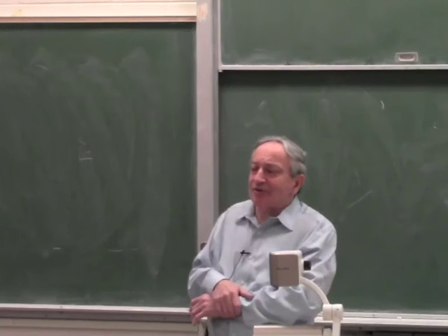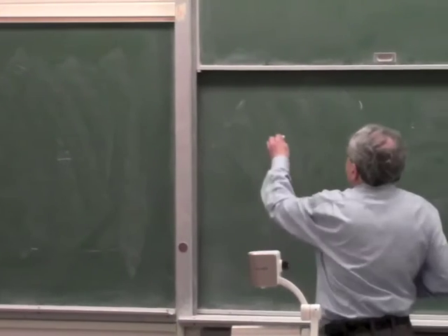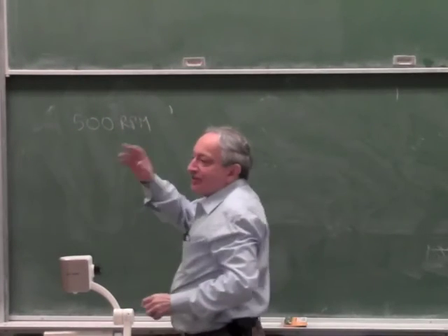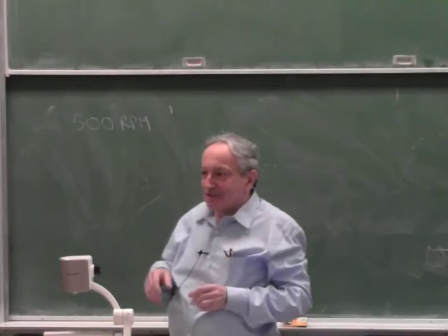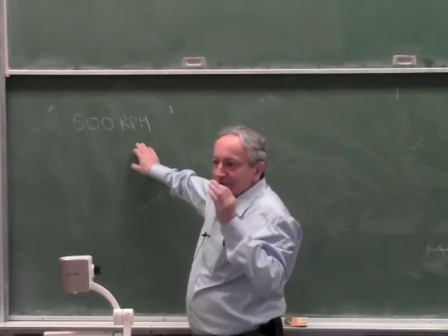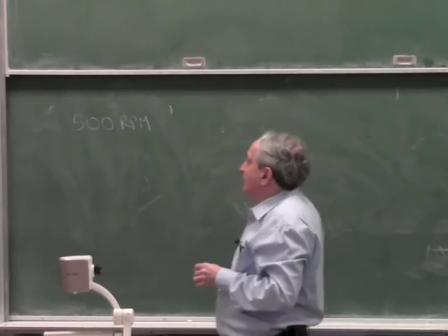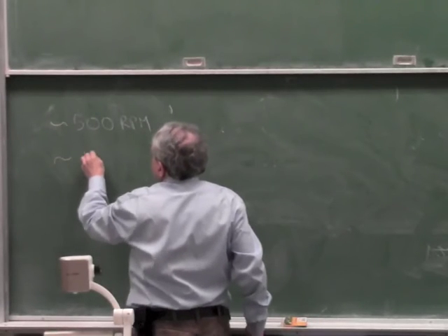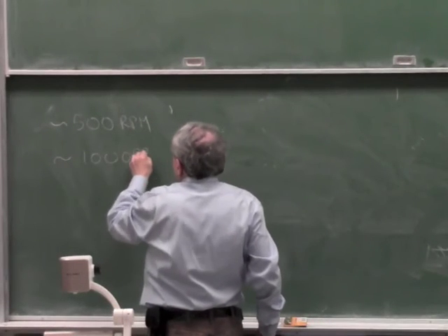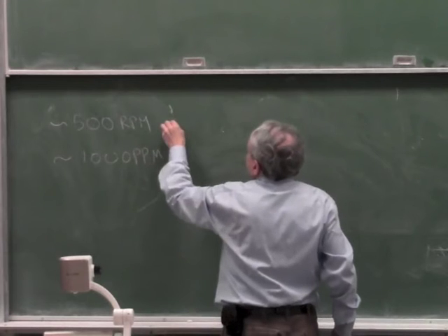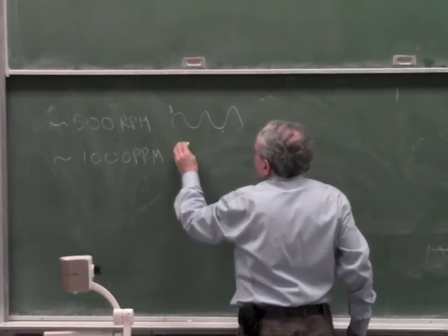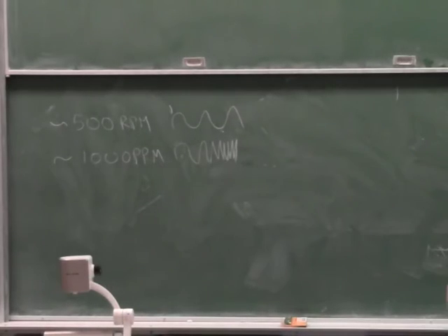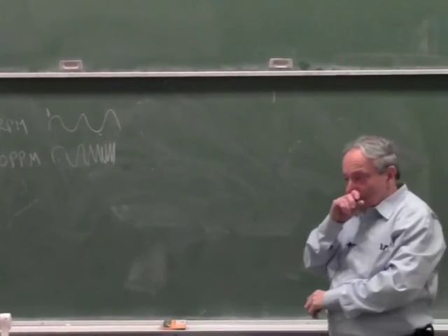Yeah, a stepper motor without ramping you can run at around 500 RPM. Of course it depends a lot on whether it has a current driver or a voltage driver and all the stuff we discussed. This is already with good driving, with almost constant current driving, okay? So that's roughly it, and with ramping maybe 1000 RPM. So this is when you apply the sine wave straight, and this is when you apply a slow sine wave which becomes faster and faster. So it's not very fast, okay?